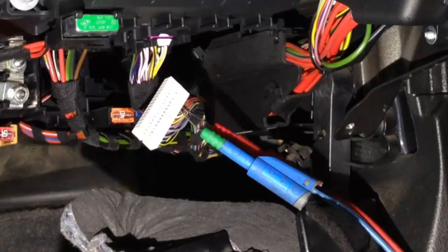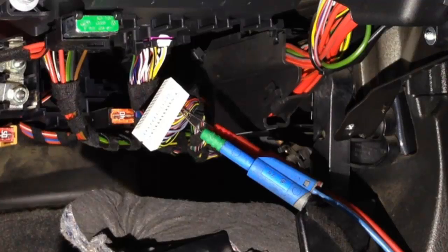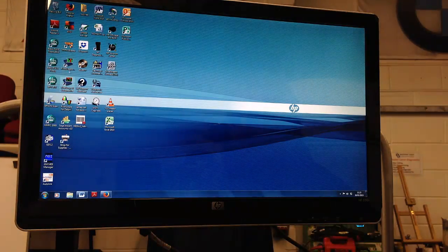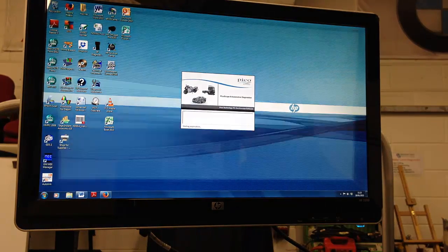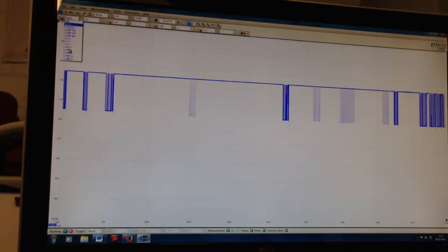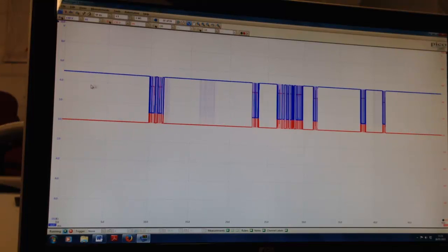Okay, so now next job, let's whip back up to the scope and have a look. Firstly with it disconnected, we'll pop the ignition back on, we'll get the network back up, and we'll just see, have we got data bus connection, what does the waveform look like, and do some basics just there. So bear with me a sec, ignition on and up to the scope. Okay, so we're going to fire the Pico Scope up now. Pico Scope Automotive. We're using the new 4-channel Pico here. Not that it makes an awful lot of difference. If you have a 2 or 4 channel, the old or the new, that should be able to cut the mustard here. We're back probing, so we're going to choose a 10 volt signal on both.